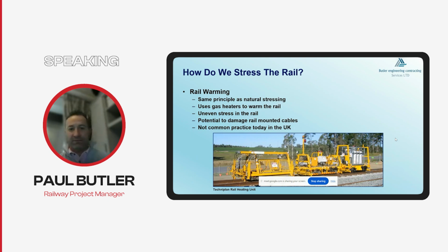Rail warming. So this is very rarely used in the UK. In fact, I've never experienced it here, but it is still used across the world. And it's the same principle as natural stressing, but all this does is use gas heaters to warm the rail. Again, you can induce some uneven stress as the rail cools after the heating process, which is why it's not quite as good maybe as natural stressing. There's always a potential to damage rail-mounted cables and rail-mounted furniture, such as axle counters and other things, because you're effectively using a flame to heat the rails up. As I say, it's not common practice in the UK today.